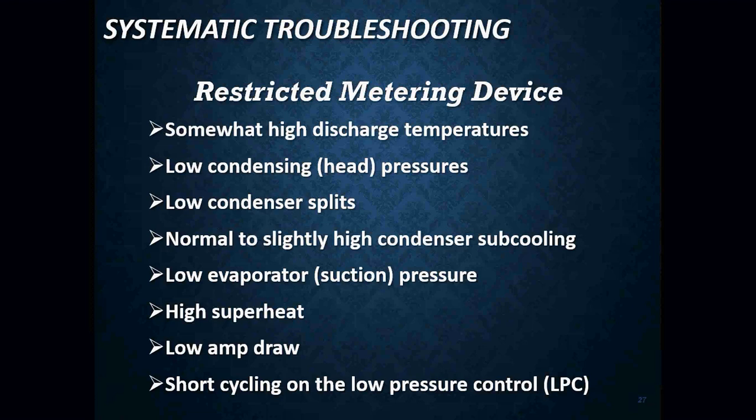Now, when it comes to air in a system, and I completely forgot to even mention this, if air is entering the refrigeration system, it's going to be because of possibly a leak, either through tubes, a gasket, or a flange. If you have a flare nut or something on there, you're going to have poor charging procedures, just simply because somebody didn't know what they were doing in the first place.